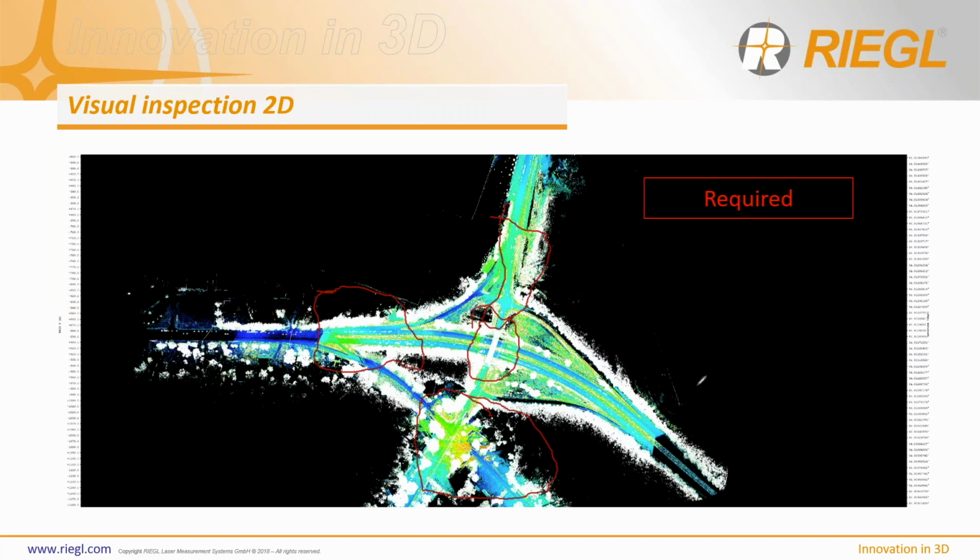So it's a pretty typical setup there. And you can see, in the shoulder here, there's the road surface on this part. If I draw that, that looks clean, the actual path. But you can see right off it is the soft target area where you're going to have some differences in the grasses due to the different angles the laser data saw it, because you probably got some shots from the highway as well as from the off-ramp and probably some from over here. So there's a melding of data there that saw different angles into the soft targets. All right, so now that I've made that all messy, I will erase my drawings.